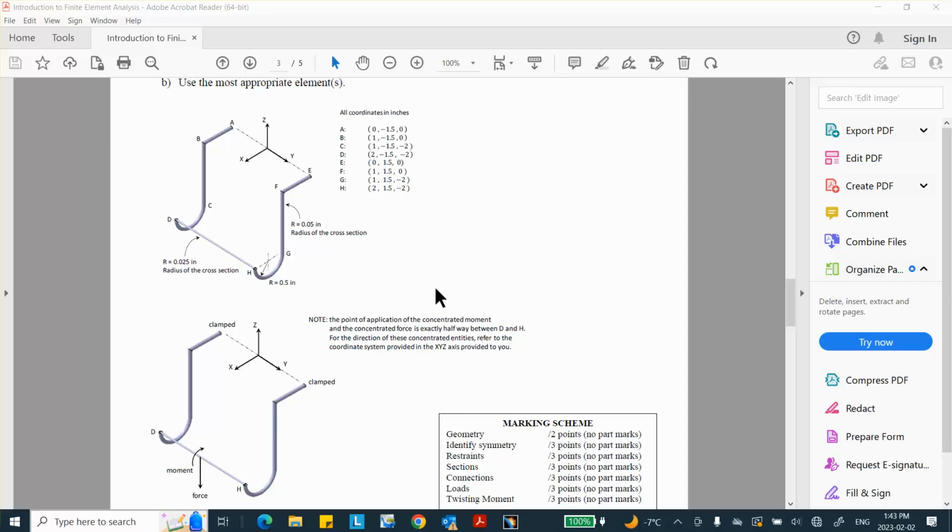Okay, so here's what I'm going to do. These problems can be done in many different ways. So on purpose, so that it's different from how number 2 was done, I'm going to create a sketch which has this entire piece in it. In other words, EFGH. So EFGH is a planar sketch, and I'm going to draw it as a planar curve in a sketch.